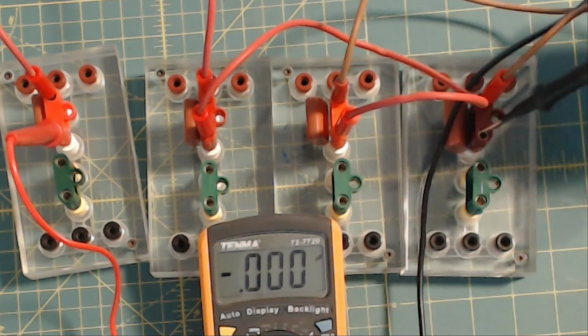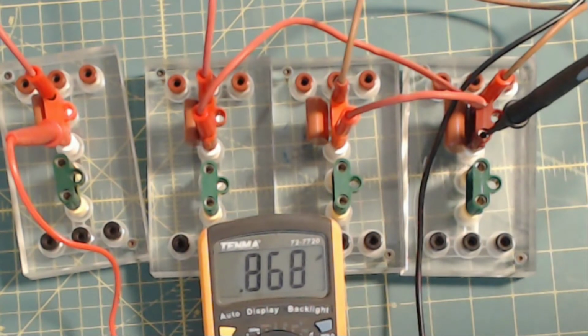And now if I put my probe here, I get a capacitance of 0.868 microfarads. And that's your job for this procedure. You're going to use the formulas and the values that I measured earlier, and calculate what the series circuit capacitance should be, C1, C2, C3, C4 in a series circuit. This is the measurement. Your calculation should, of course, be close.